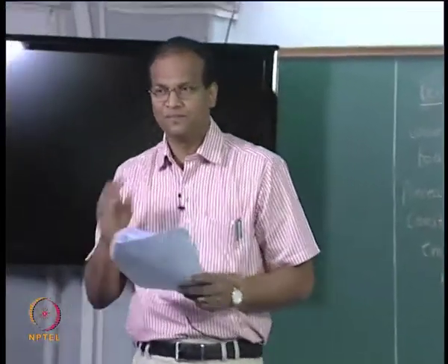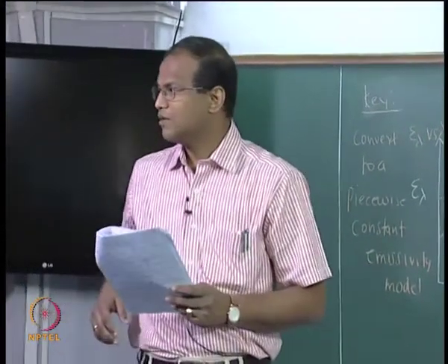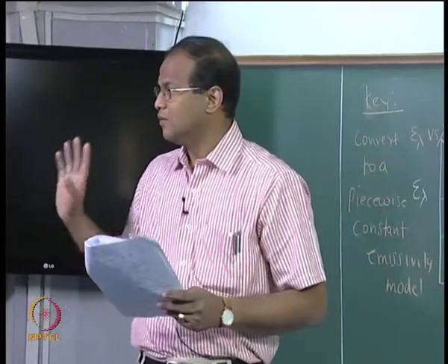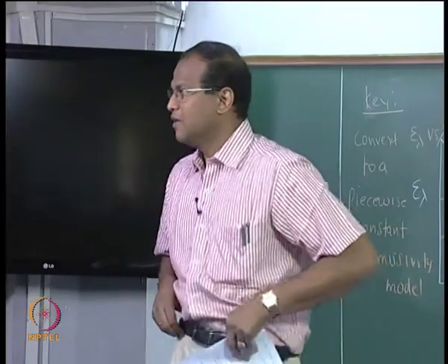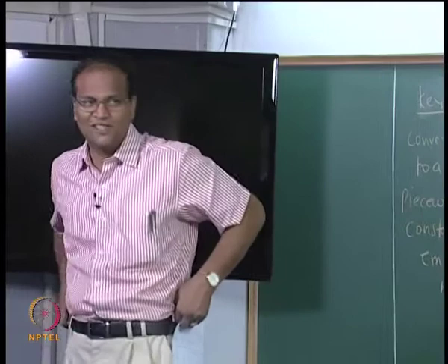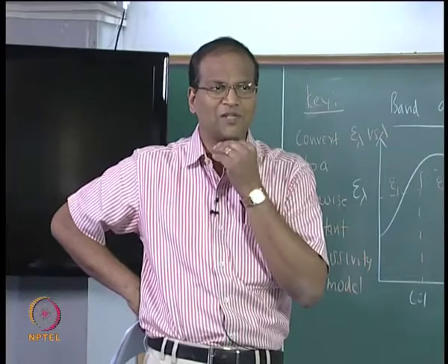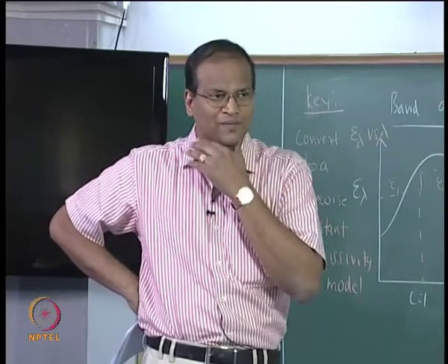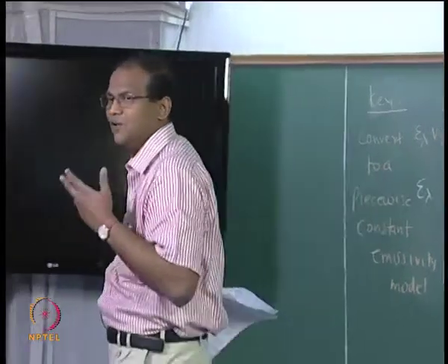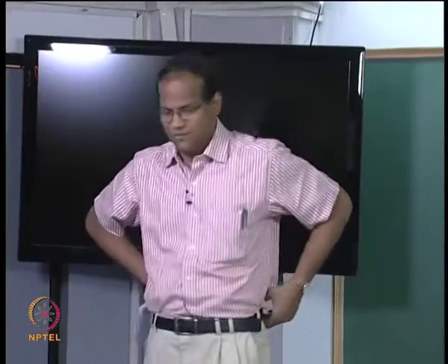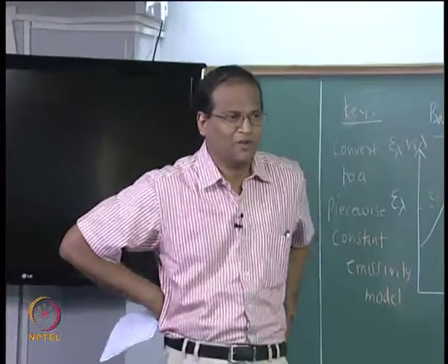Problem number 30, 35. Sir, this graph is same for all the surfaces in the enclosure? No, it need not be. If it is same, very good for us. Then can we just calculate the total hemispherical emissivity and do it with the previous method? I think we have to check this. What he is saying is every surface has like this. Can we just calculate the hemispherical emissivity once you know the temperature? It will give some answer, but I don't know whether it's 10%, 20%, how far it is off. If they have exactly the same properties, then it will come, but we will have to do an exercise and find out.